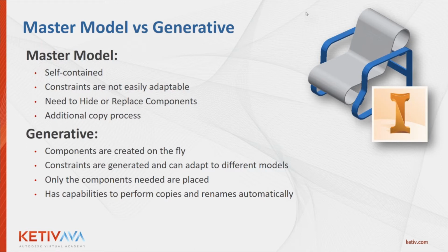And the final comparison is that we have the capability, using the Inventor API along with iLogic, to make copies of the components of the assembly and rename them automatically, not just the browser name that you're seeing inside Inventor, but the actual physical file name. In our example, we're going to use a project number and a project folder. The folder is going to be generated, and all the parts are going to be generated with this particular project number.